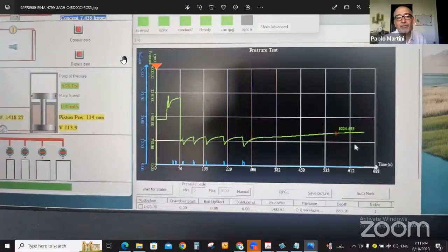So there's microfiltration from the borehole into the packer, to the probe, basically. And if you stayed until many more minutes, you would end up with the hydrostatic pressure. So I would interpret this as a seal failure.